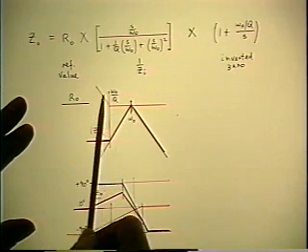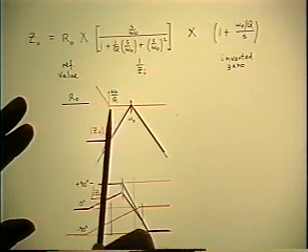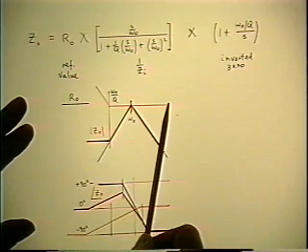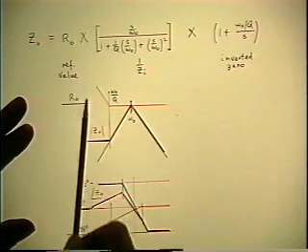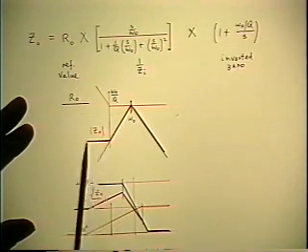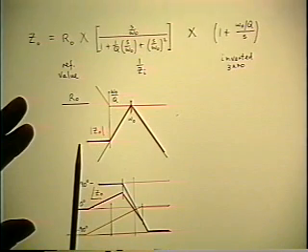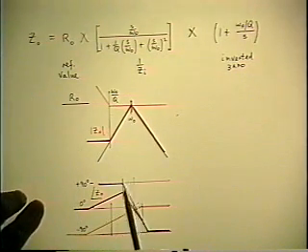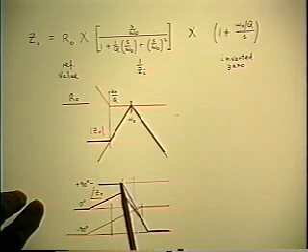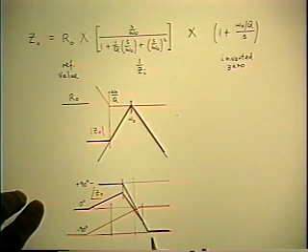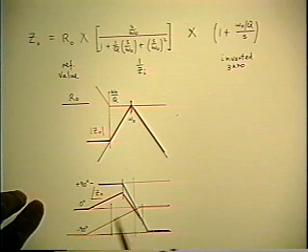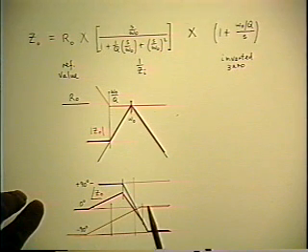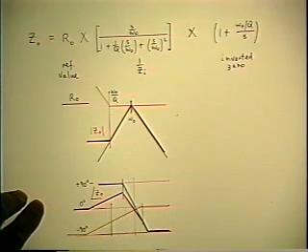You follow the blue line where the orange line is unity, and when the orange line curves up with the 0, that'll flatten out the low frequency asymptote. Same with the phase. Now I have superposition of a second order single slope and a first order single slope, plus 45 per decade, and the red line is the combination of those.